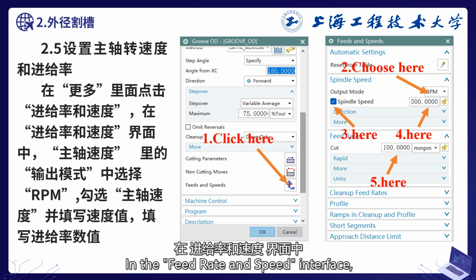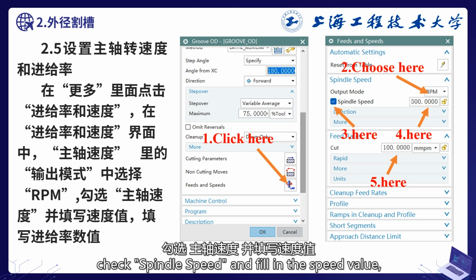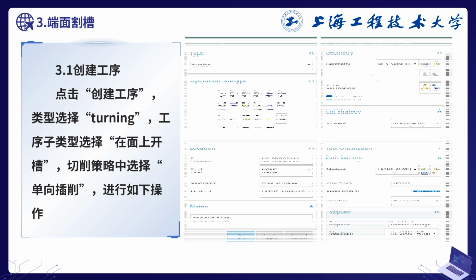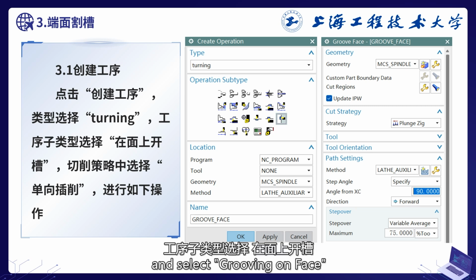In the feed rate and speed interface, select RPM in the output mode of spindle speed. Check spindle speed and fill in the speed value, and fill in the feed rate value. Finally, we perform the face grooving operation. Click Create Process. Select Turning for the type, and select Grooving on Face for the process subtype.